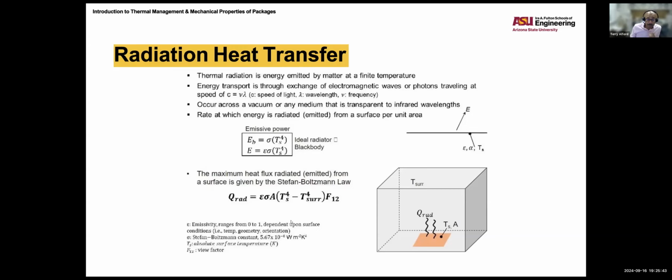That's where you get such a large flux of electrons, with the material at elevated temperature, that those electrons can transfer momentum to the metallic atoms and cause them to move or diffuse.